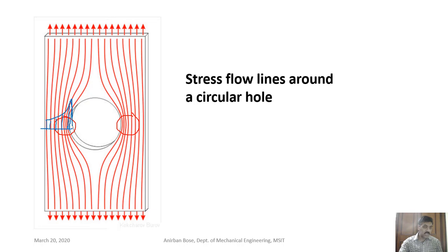Here you can see the stress is very high, large stress, whereas far away the stress is gradually decreasing. Similar thing will be in this section also. So this is the maximum stress that will be developed very close to this kind of discontinuity. Here in this case it is the hole. The similar thing will occur in the case of notches, fillets or other changes in the component.